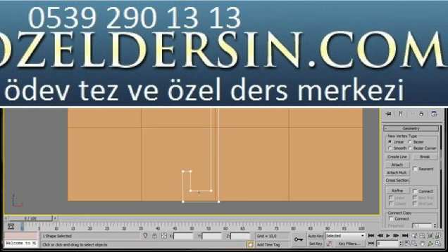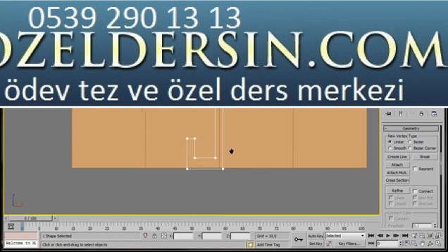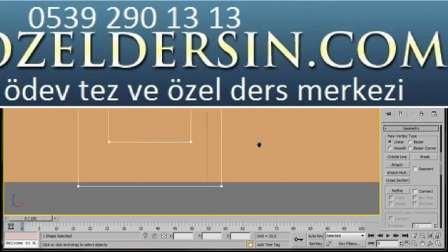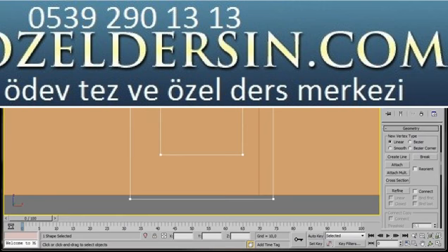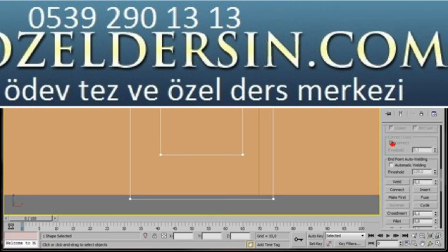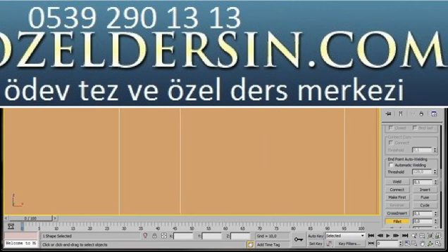That's fine. Now I shall go back up to the subdivision mode and I'm going to select vertex again. Let's zoom in closer so we can work on the tip of the handle. I'll select these two vertices. I'm going to scroll down now into geometry and I'm going to click on the fillet tool. Now all I have to do is drag the cursor up. There we are. Notice now that our two vertices have just joined together.